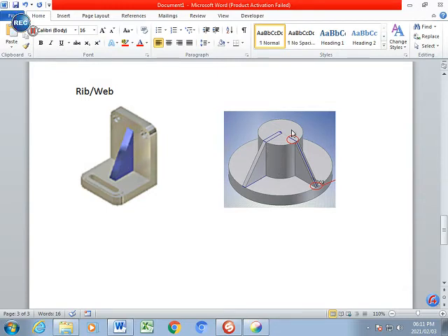Right, here the same thing. There's a circular base, and there is a circular component on top of the base, and to secure that you will put a rib like that against the upright and the lower part, which is the horizontal part of the base. It's normally welded here, and the function is to ensure reinforcement. Ribs or webs can also take other forms of shape, but you will easily identify it as it always is situated in the middle of two main components.